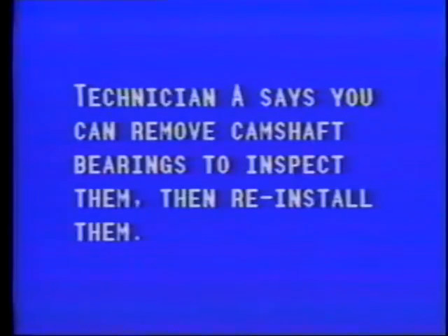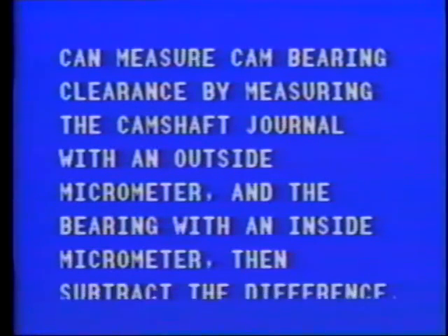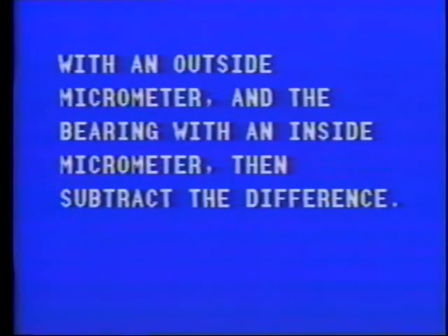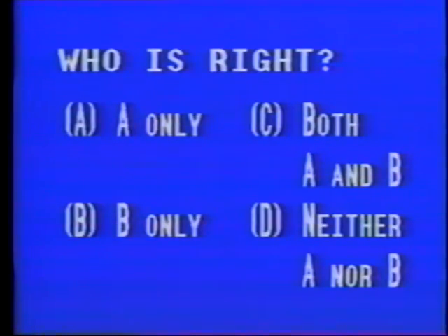Two technicians are discussing camshaft bearings. Technician A says you can remove camshaft bearings to inspect them, then reinstall them. Technician B says you can measure cam bearing clearance by measuring the camshaft journal with an outside micrometer and the bearing with an inside micrometer, then subtract the difference. Who's right? A only, B only, C, both A and B, D, neither A nor B.